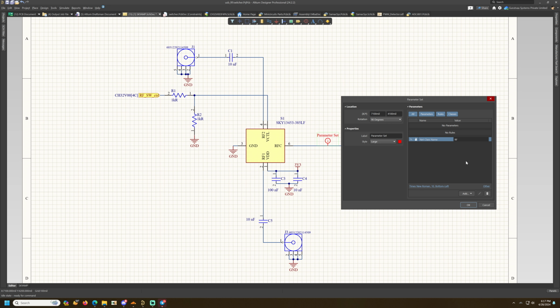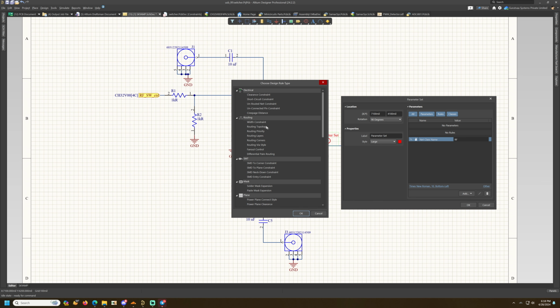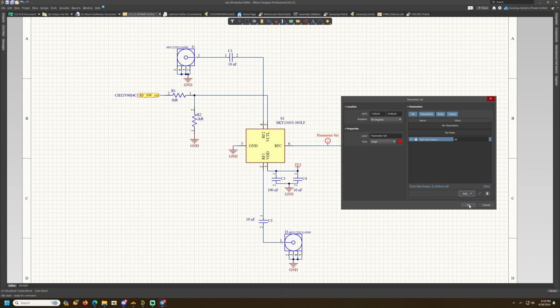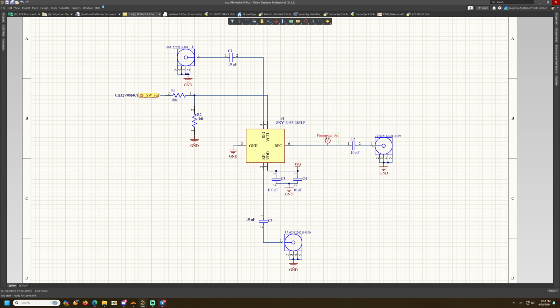The datasheet suggests that we connect DC blocking capacitors on each RF port, and if you know the internal structure of an RF switch, it makes sense to connect DC blocking capacitors on all the RF ports. Also, we do not want any DC coming in or going out from these RF ports, which can affect the normal operation of the RF switch.